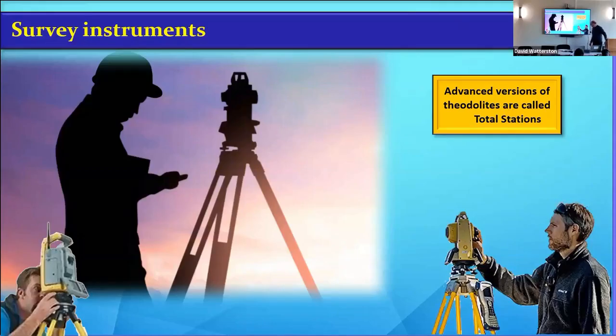So what do we use? Well, we use theodolites basically, which give you a horizontal angle, a vertical angle, and a distance. And in the old days, you used to have to fiddle about with it, use micrometers, use bubbles, split bubbles, and then tape out the distance, or use it with tacheometry or some other method. Nowadays, they're known as total stations, and they're fancy pieces of kit. They've got reflectorless lasers on them, and Bluetooth or radio connection, and they can work down to a millimeter in distance and a second of arc, which is very, very precise.